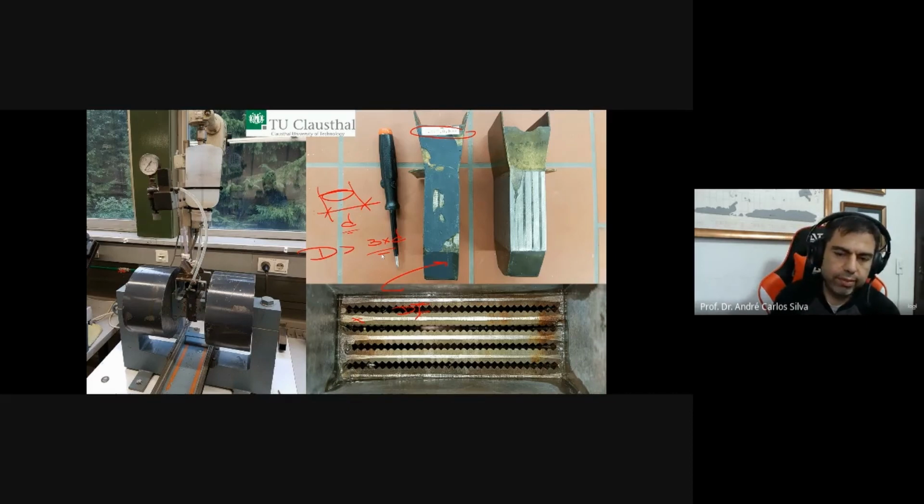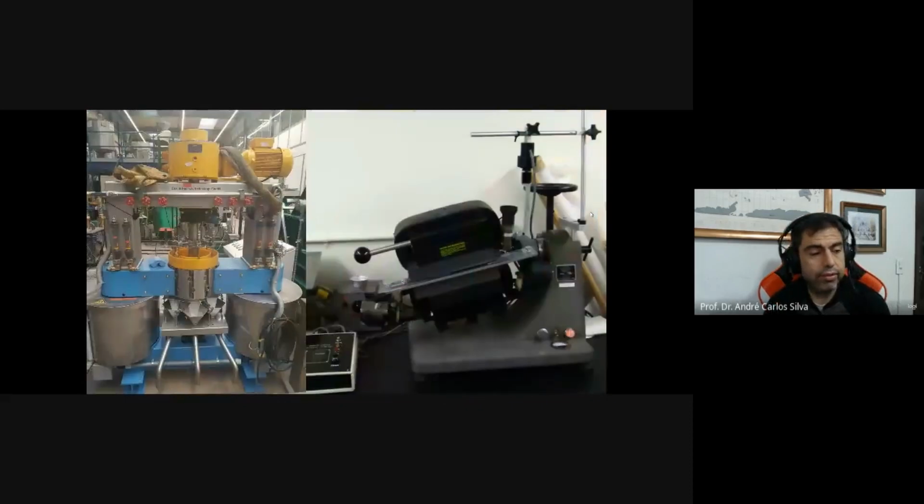And another thing important regarding matrix, because I have different kinds of matrix, like steel balls, steel wires, or even like steel cloth I can add inside of this machine. Okay, in this case, the magnetic field is going to be convergent. So I have one pole in here and another pole in here, and I have what I call the power of the tip, because I have a convergent magnetic field over here, and this increases my magnetic field a lot. Okay, so always try to use matrix like this, and you're gonna have a very good result.